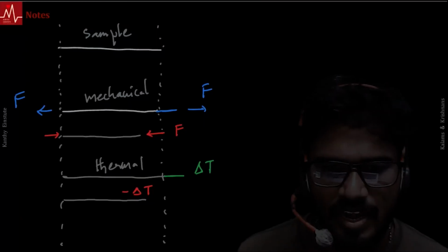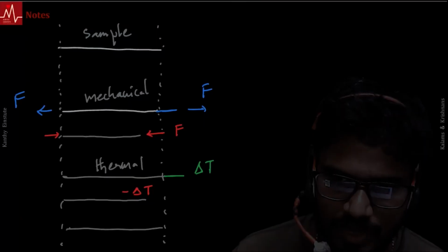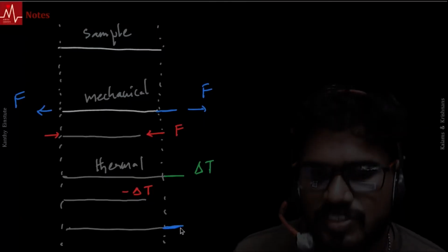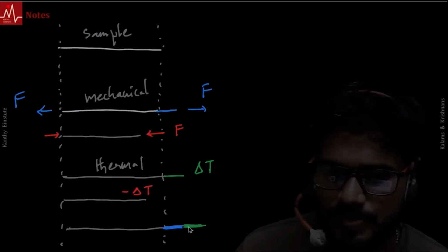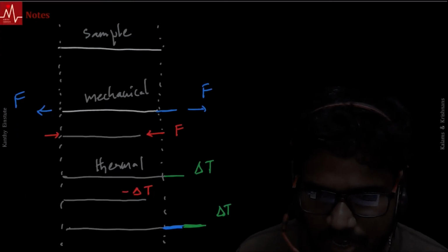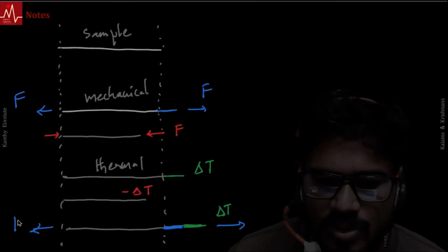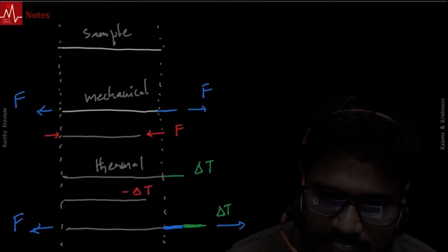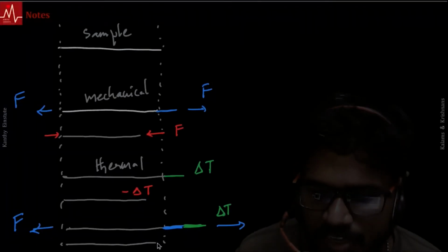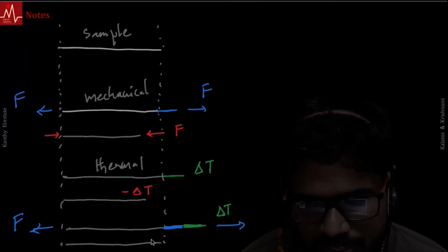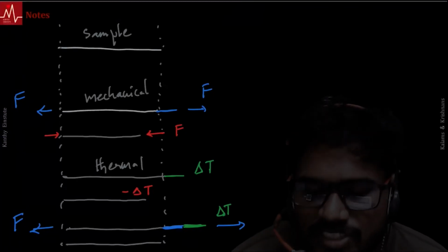Now, the sample can have both mechanical force applied. There is a change in length due to that, and there is a change in length due to temperature. So I heat it plus I pull it. That scenario is possible. Notice there is a very peculiar scenario where I pull it and I cool it down. It need not have a change in length.